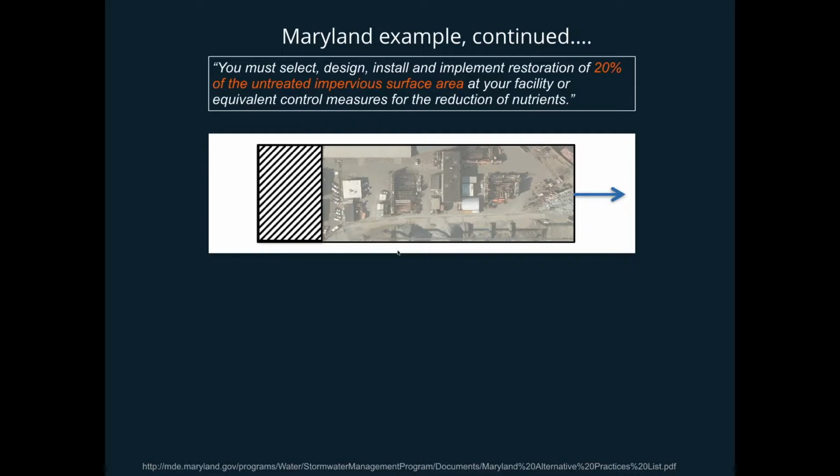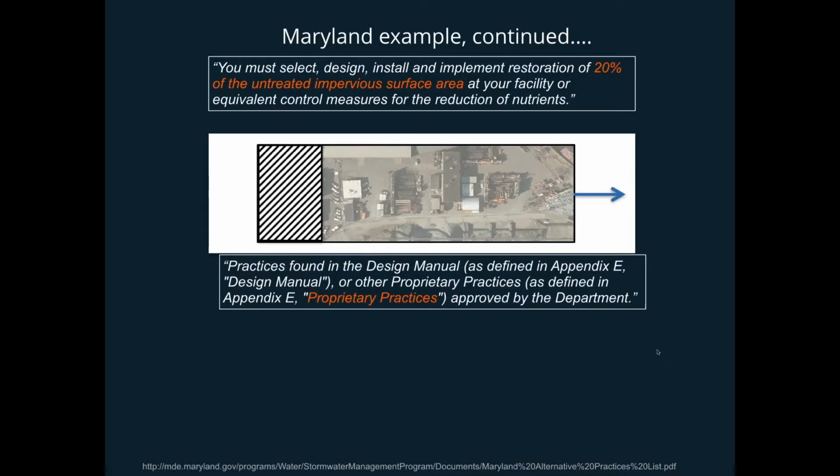So within your industrial stormwater permit, they're talking about TMDL, a regional program to help bring Chesapeake Bay effluent pollutant concentrations below your permit benchmark, your permit NAL.